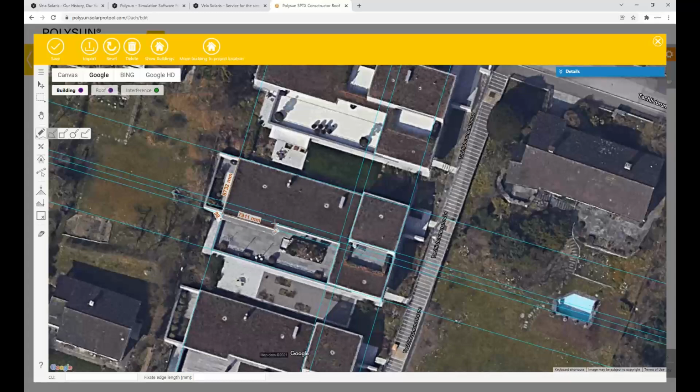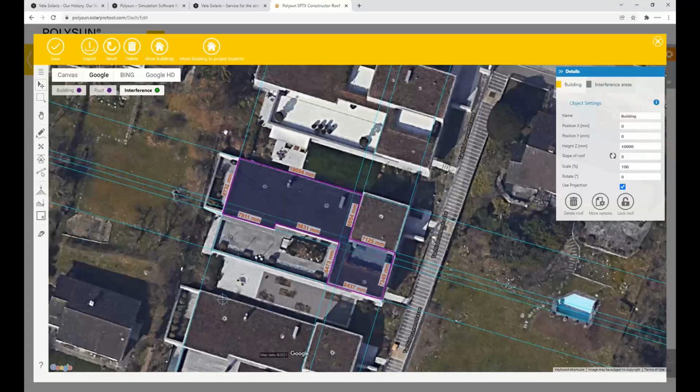And you can see here I have actually forgotten one, but by pressing Shift again, we can easily have the 90-degree angle, which is also displayed here, and just keep following the points until the whole roof is drawn and all is rectangular. Perfect. So now we're set up here, and we can see the height of the building.